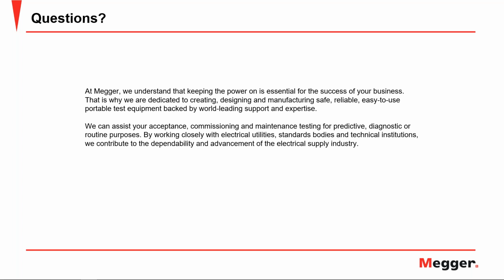We have this debate. We have had it many times, obviously internally and with customers. And yes, when we are testing with primary injection, we are stressing the circuit breaker, right? Because, as I mentioned already, the actual definition of testing with primary injection is duplicating the conditions of fault in service. So yes, you are stressing it.